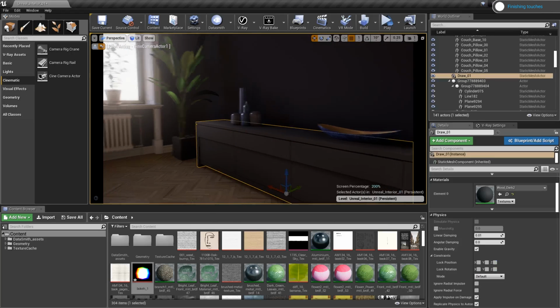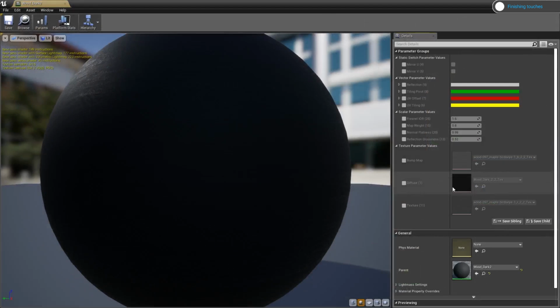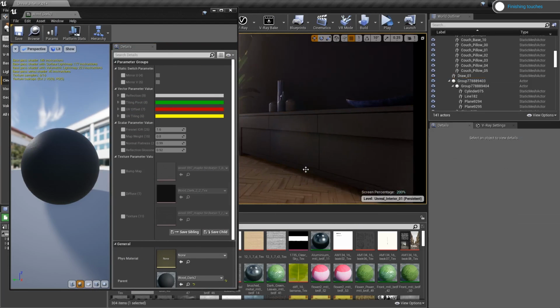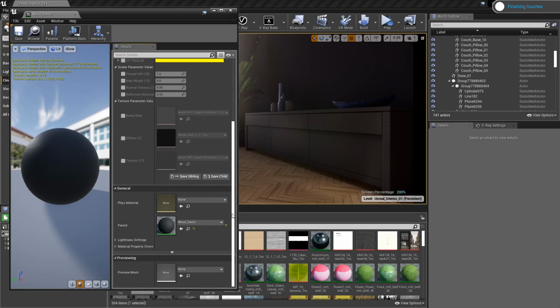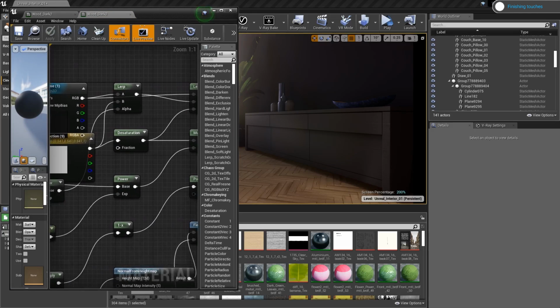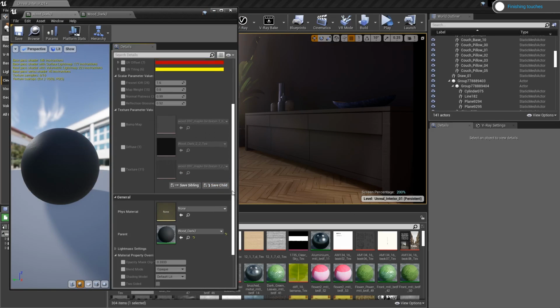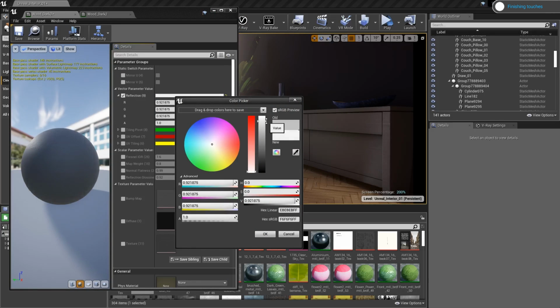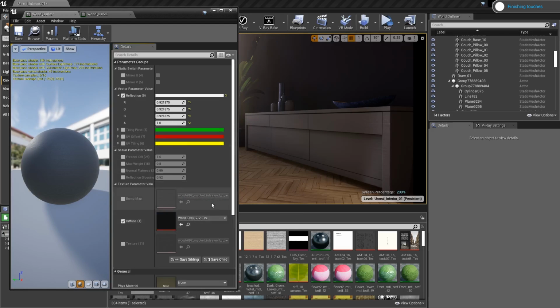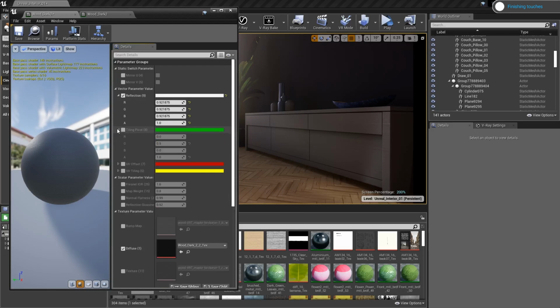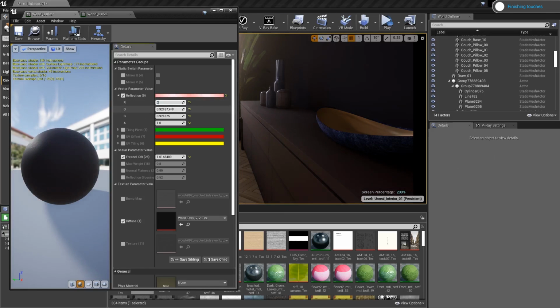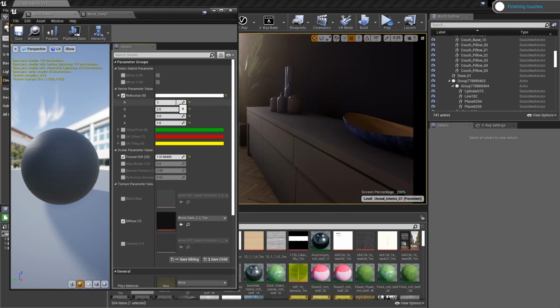At this stage, I can go ahead and edit in real time the materials in the scene, and make them look more reflective or make some additional tweaks to them to get the final look that I desire, since the post-process effects will drastically affect the look and feel of your materials. Also, tweaking the materials at this stage does not affect your light maps, and having reflection capture actors will give you a more precise idea of how your objects will react when you play with their reflections.